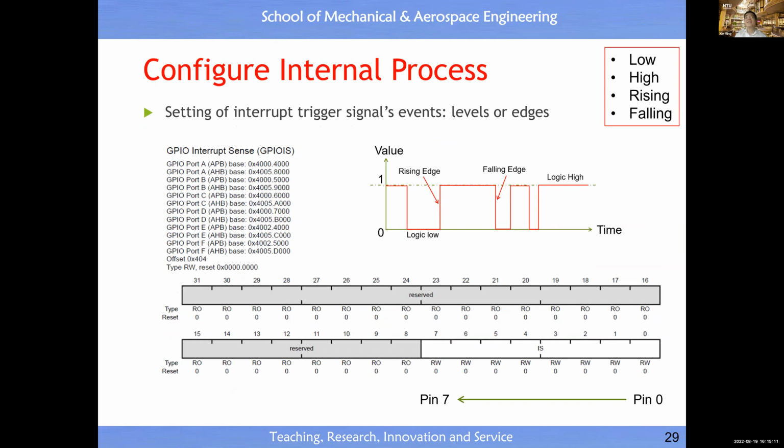In case it's a flow in, like I press a button because something is urgent, stop everything, then you must tell whether the microcontroller responds when it sees a level, or an edge: rising edge, falling edge, or level high, level low.